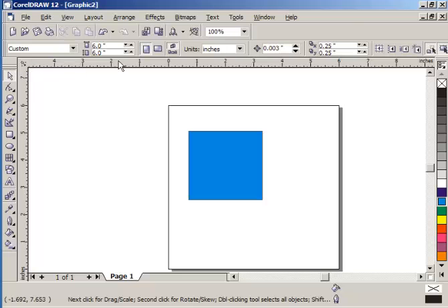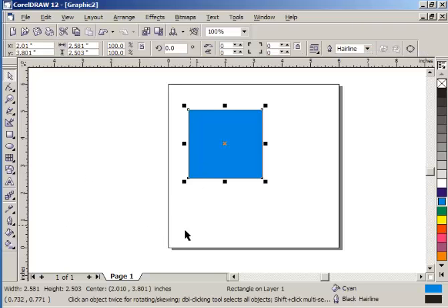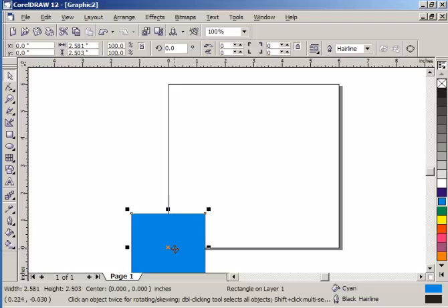Down here is our ruler, and if you look at CorelDraw with our ruler, we have our horizontal and vertical, and right now if you look at 0, it's down here, and then 0 over here, so that's our 0,0 coordinates. So we can navigate through and type in where we want to place an object at a time. If I literally type in 0,0, you can see this box going right to this corner, and it's the center axis that it actually navigates to.